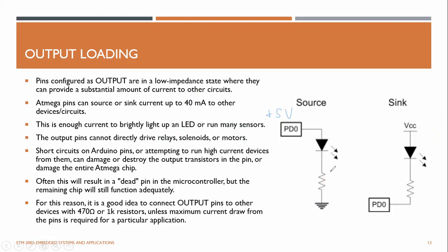So you just remove this LED and resistor and just short circuit, right? Sometimes that impedance is too small, which means you are driving to the maximum potential or maximum current. Maybe if you drive it for too long, that will potentially kill this pin, right?